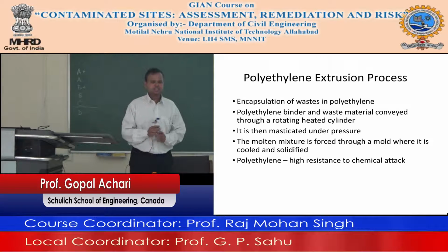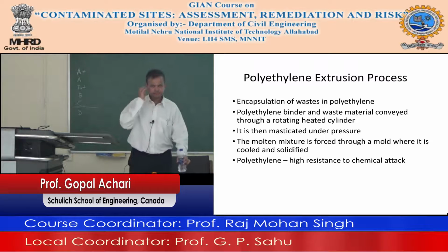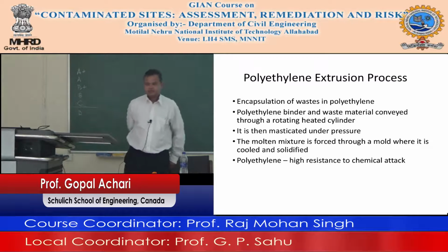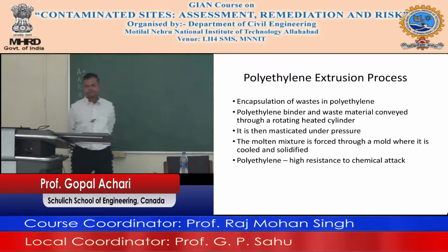It's called the toxicity characteristic leaching procedure, TCLP. You have to conduct a TCLP test. It's not that I put it in water and shake it for 2 hours. It's not that. You have to actually conduct a TCLP test to show that it is not leaching.